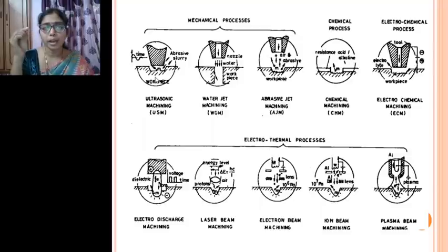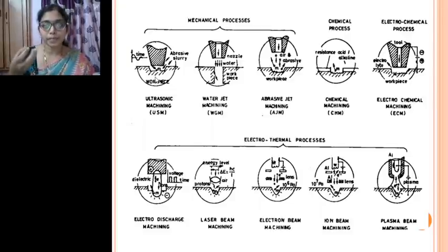When a particular point comes and hits the surface, the material will go beyond its shear strength, and then shearing of the material will happen. The strength with which this particle hits the surface will become more than the strength of the material. It reaches beyond the strength of the material. When that happens, material removal will happen, right? Crack propagation will start, and the material will come out from the surface. So such a thing will happen in the case of the ultrasonic machining process.